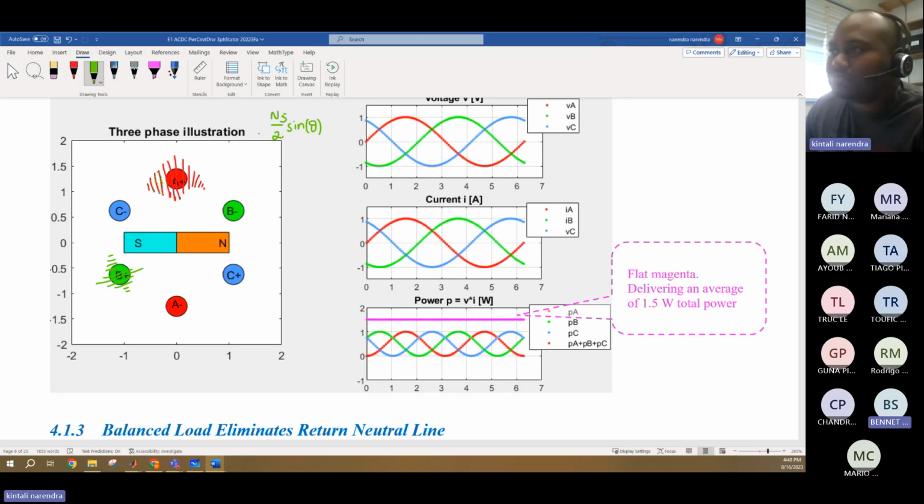Now, as I said earlier, there is only one copper wire. You're not using so many copper wires. One copper wire, in this slot you're doing one winding. So imagine the current you're providing is entering here in this slot. Now there is only one winding, so the amount of total current will be less. Here there are three windings, so the amount of current is varying depending upon the number of windings. So into phase current, I'm just considering the magnitude.